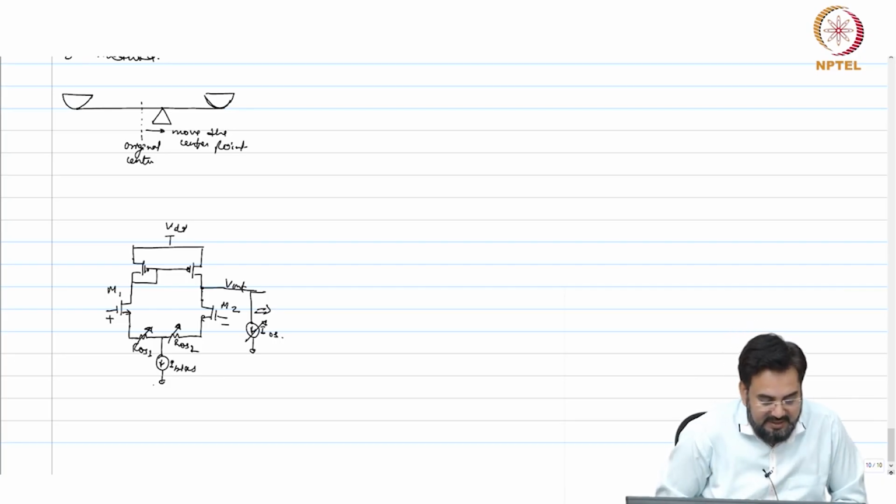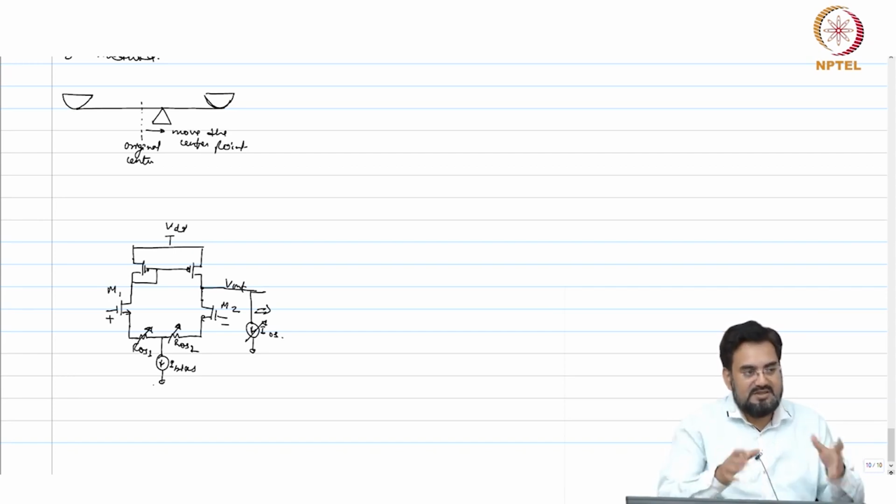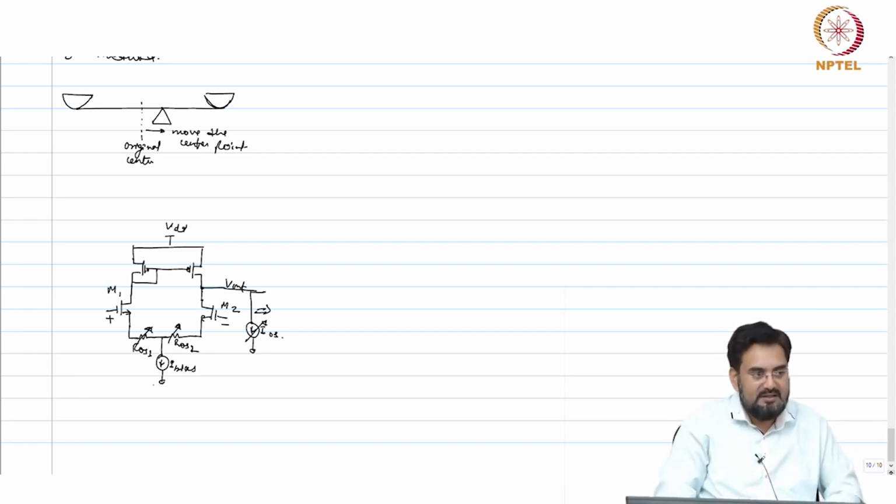Designing a very low value of resistor, order of ohms, on chip is not easy. I mean, you use a metal, but kilo ohms of resistor comes mostly from poly resistors, and if you are using, let's say, 10 ohm or something using poly, its size becomes very huge, because the width needs to be very large. But kilo ohm will take very low area and you can easily do it without any problem.